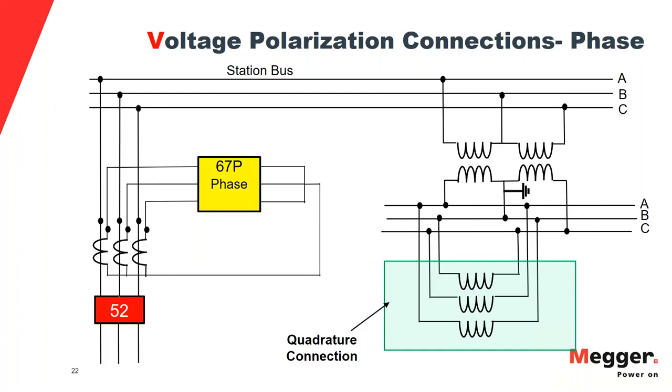Okay. Next question. When performing in-service measurements on a directional relay with quadrature connection, would it be correct that the IA load current would typically lag VBC by 30 degrees if the load is at unity, assuming ABC sequence? I would say it will lag 30 degrees by VA, not VBC. VA and VBC in the ideal world are lagged by 90 degrees. So probably VBC would be a 60 degree difference from IA.